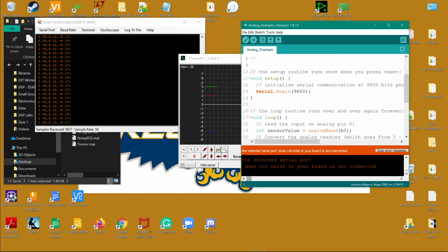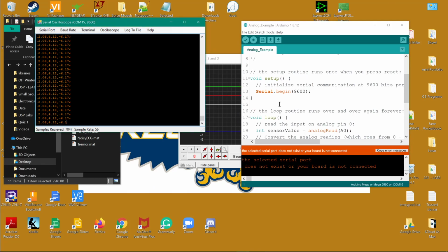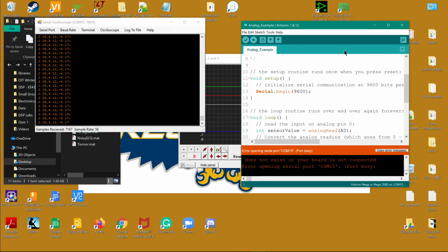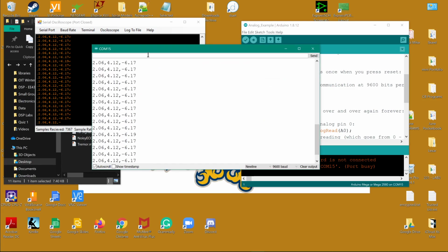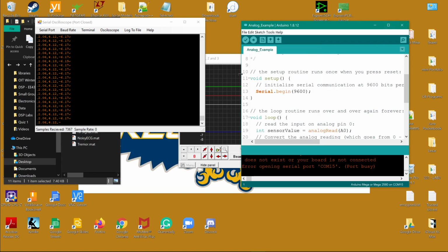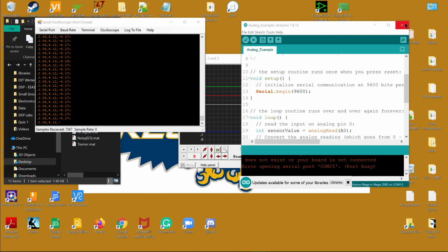And that would be the reason why, if you had some program where you could type in values on a serial port and send them to adjust the function of your controller, then you would need more than one serial port operating at the same time. You would need one of those FTDI boards.